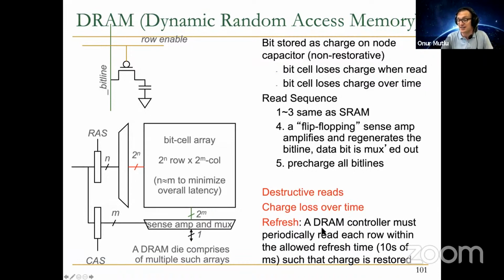And we discussed this. If you want to go back to lectures 2 and 3, for example, we discussed DRAM refresh, and you can refresh your memory about this. No pun intended with refreshing your memory. But basically, a DRAM controller must refresh all of the data in all of the DRAM chips every 64 or 32 milliseconds, sometimes every 16 milliseconds at high temperatures today. And that's unfortunate, as you can see, and that leads to energy and performance overheads.